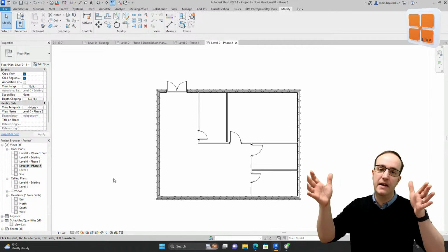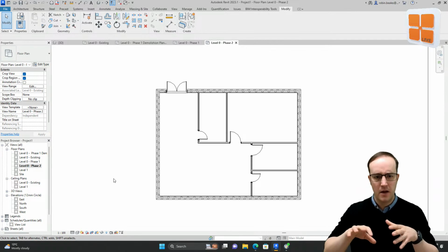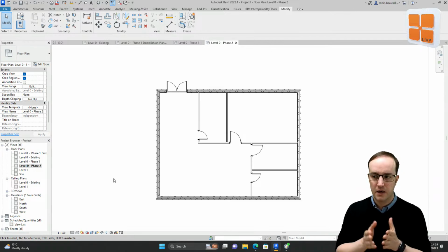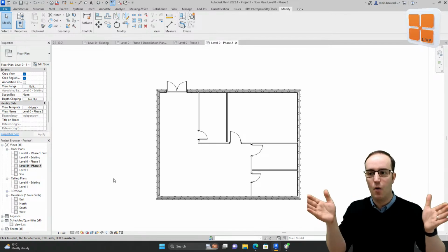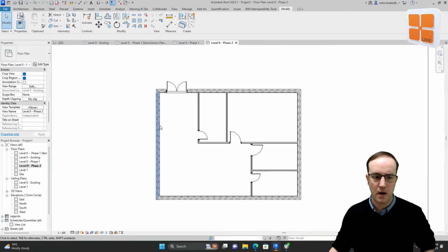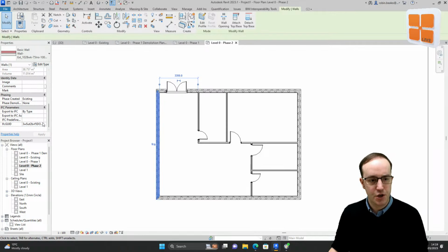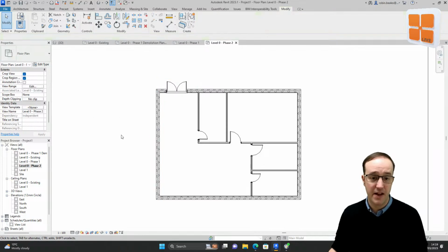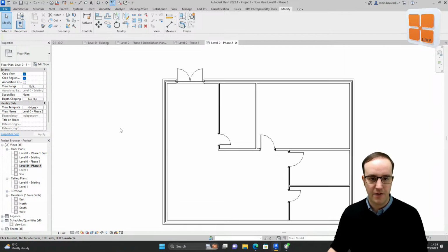And you can create as many or as few of these as you want, and again go around and configure the colors, the shading, and the override on the graphics. So it's quite easy to go through and configure how my project is going to work. And it works quite well. Again, set up your phases, select your objects, add your phases to your objects, and then tell your views what you do and what you don't want it to show. The main thing is to get that right.